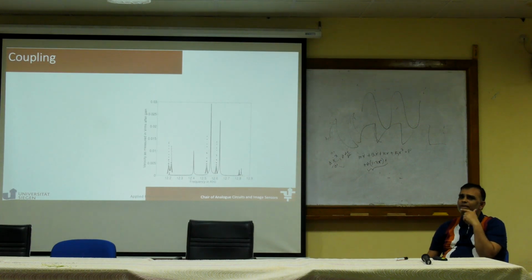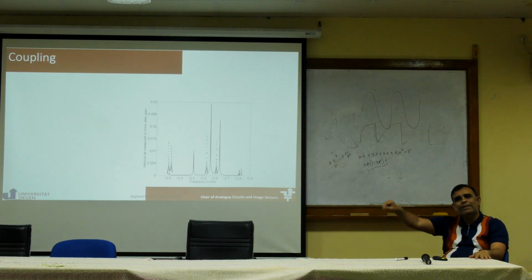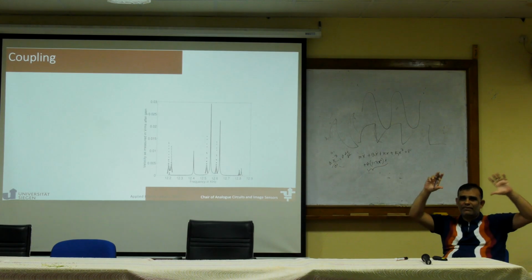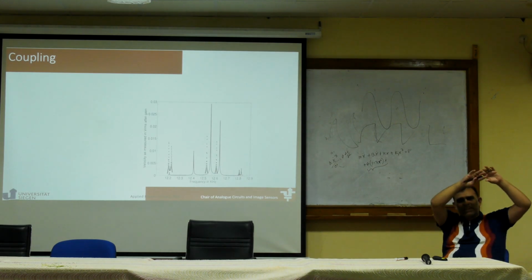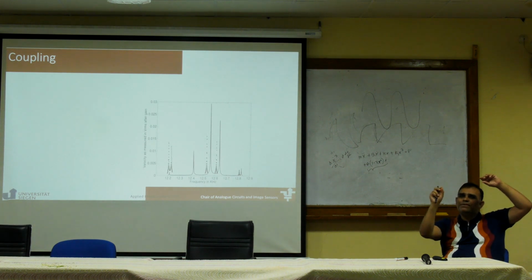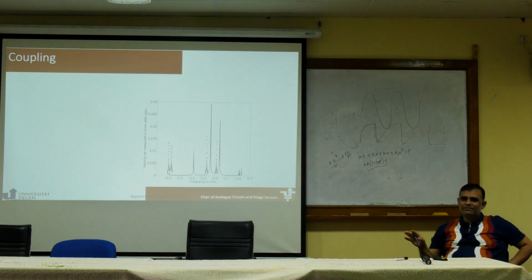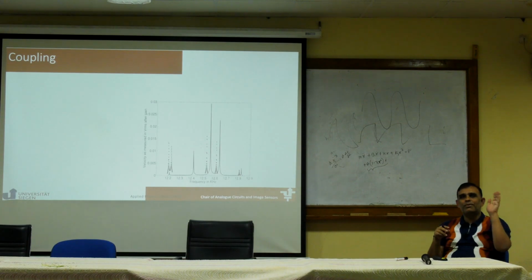The other thing which we know is the frequency at which they move is the eigenvalue of the system. If any one of my resonators changes, think of a matrix, right? If you have a 5 by 5 matrix with elements only on the diagonal or an off diagonal, if any one value changes, my eigenvalue changes, right? Now, my eigenvalue is the resonance frequency of the system, which I can measure from the response of any one resonator.